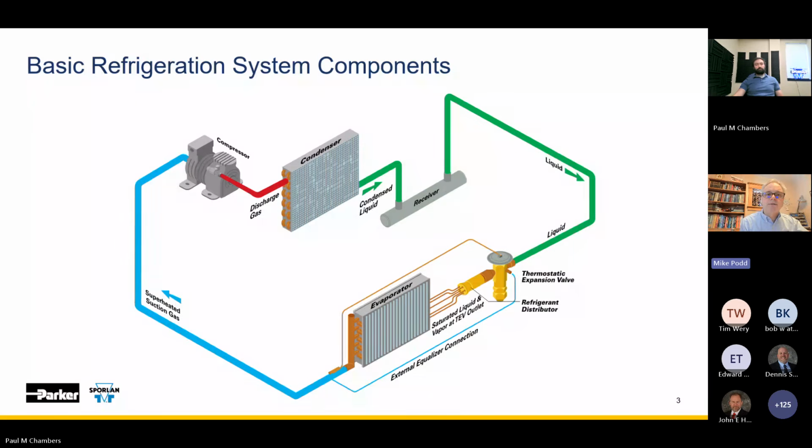And the condenser is sized to condense the liquid so that it can be carried to the expansion valve and do the work. So on a design day, that will typically be your hottest day of the year, right? Okay. So what happens as temperatures go down is that now your condenser starts to become larger than required.